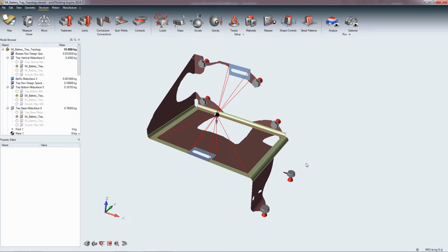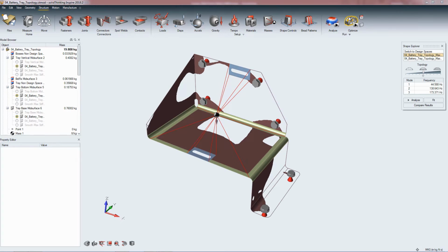Here is the optimization result. We can review it here. And we can drag this bar to have a little bit more material and a little bit less material. It shows me the importance of the material. Like on the very left-hand side, the material is the most critical one. I'm staying at the middle for this bar. And you can see the first mode frequency is 44 Hz, still above our requirement.